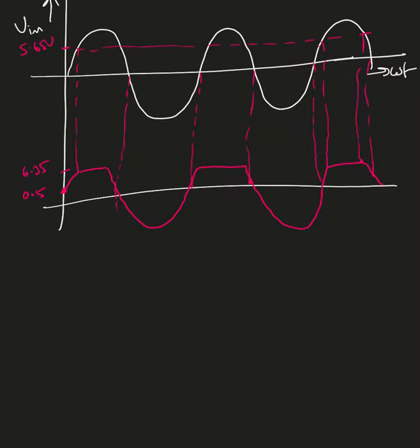Now from this I'm going to draw the transfer characteristics. So my input is varying from +10 to -10. So here is my input, a dotted line. Now my output is going to start at, it's not 0.5, it is 0.7.